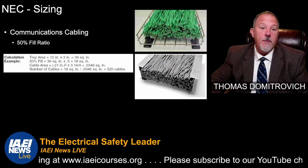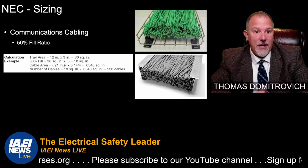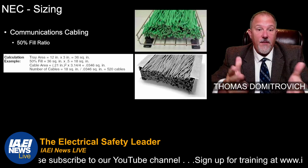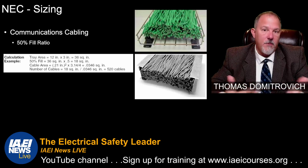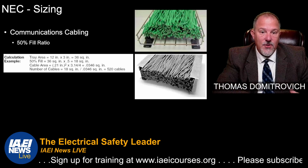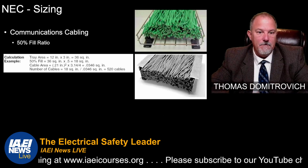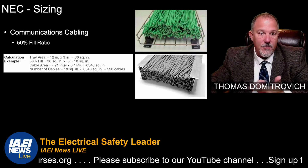Communication cables, 50% fill ratio. This is how you do your calculation. You take your tray area, say a 12-inch by 3-inch is 36 square inches. You do 50% fill. So you take that 36 divided by 2 or multiply it by 0.5, and that's 18 square inches. Then you do your cable areas and make sure you don't exceed that 18 square inches. And you can do your number of cables. Those are your data.